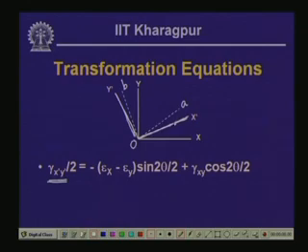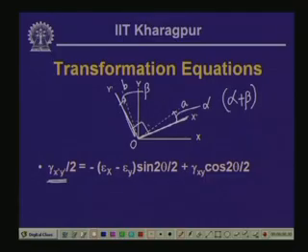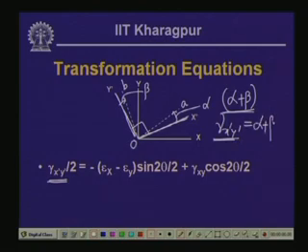Now, because of the shearing strain, they have undergone a change, and let us call this angle as changed angle alpha and this changed angle as beta. Thereby, the total change which is alpha plus beta from the original 90-degree of OX dash to OY dash, and this change is the shearing strain gamma x dash y dash. So, gamma x dash y dash is equals to alpha plus beta.